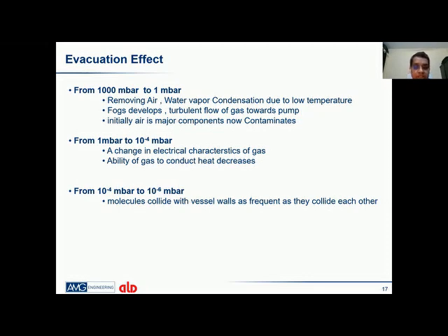So this is just to represent that thing only. When we are dealing with the furnace at the 10⁻⁴ and the 10⁻⁵ level, in most of the brazing applications or the different applications of heat treatment, at that level there is no air inside the furnace. It is only the contamination coming with the parts, some amount of water vapor, and sometimes during the operation, in production, somebody is touching the hot zone, something is left inside the hot zone. These all play a very important role when we are generating a vacuum.